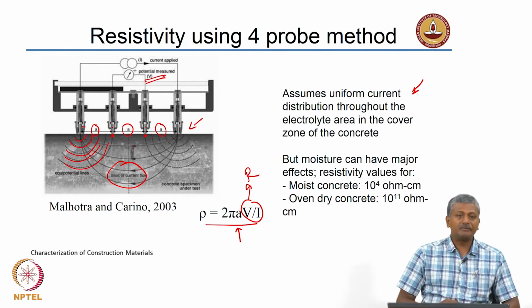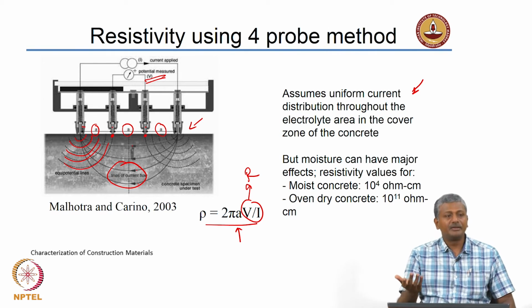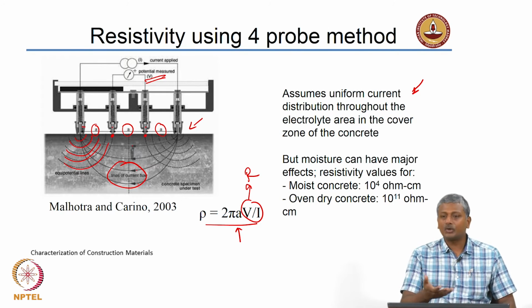However, given the fact that the Wenner probe can also be used in the field, people generally tend to have this equipment quite handy in most labs, and because of that it is quite useful to actually conduct the conductivity or resistivity determination with the Wenner 4 probe equipment also.